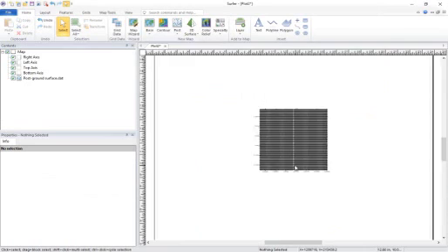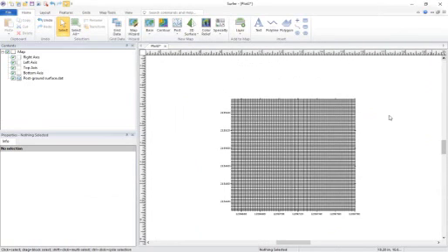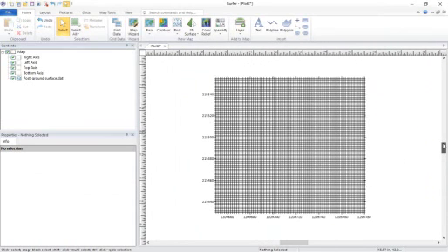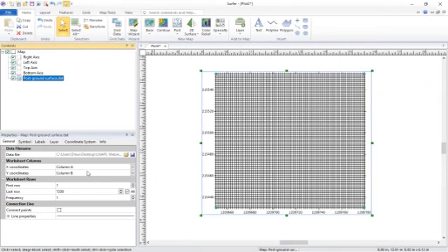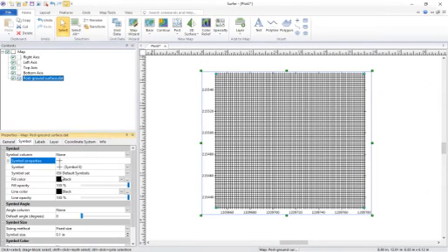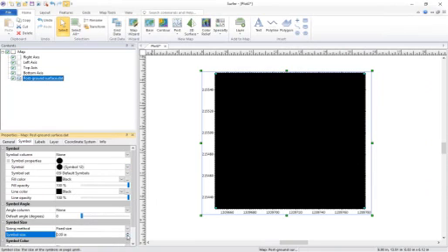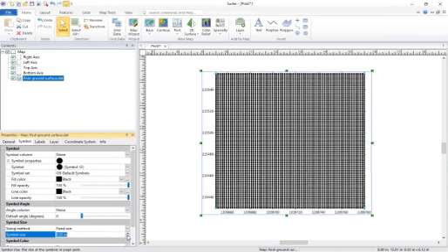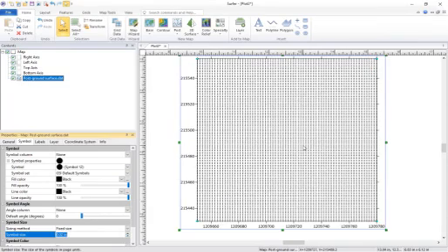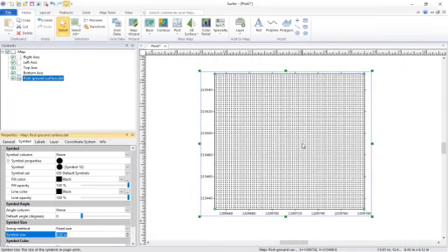And so now we can see a post map of these data points. Change the symbol here just a little bit so we can see that they're all points, and reduce the size here, but I'm showing this to show you the sheer number of points that were used to create this ground surface. So in order to create the ground surface, I need to grid the data. And this can be easily done in Surfer.